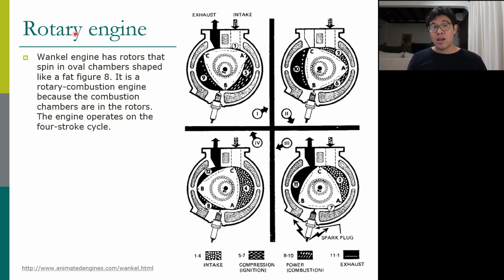It's not only that. In typical rotary engines, they have 2 rotors, which means that in one round it has 6 power pulses. So that's why it has a lot of power. But it has the same drawback as the two-stroke engine. You cannot control the amount of air fuel. You cannot control the combustion very well. So you use a lot of fuel and you create a lot of pollution with this engine.